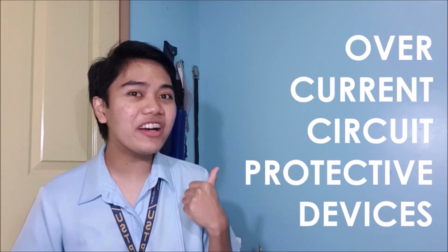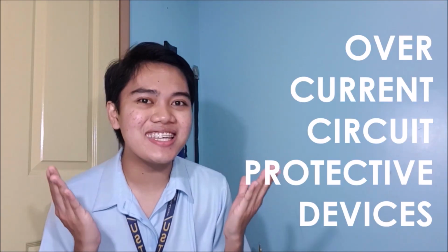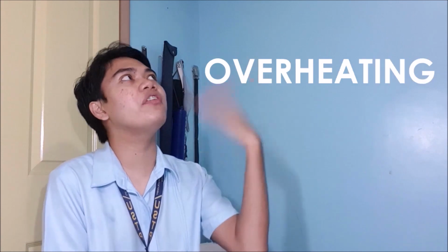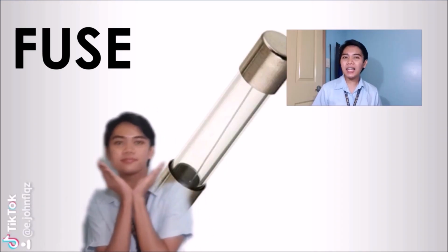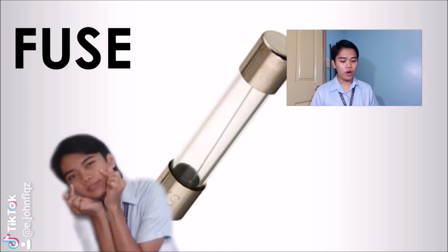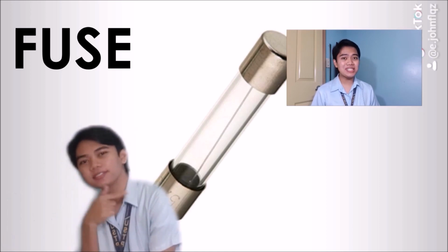Now let's tackle the overcurrent circuit protective devices. The main purpose of this is to protect insulation, wiring, switches, and other apparatus from overheating or burning by cutting off the circuit. Example, fuse. It has an alloy link of wire with low temperature inserted into a circuit. Therefore, all current must pass through this metal.